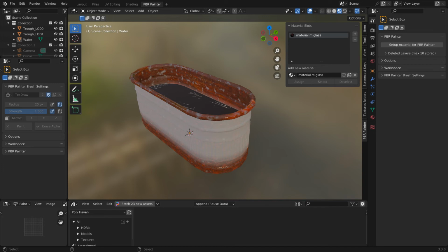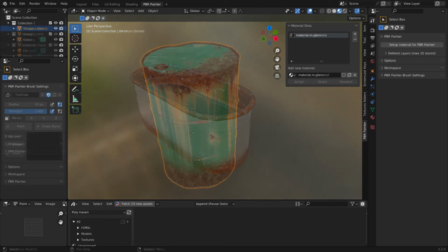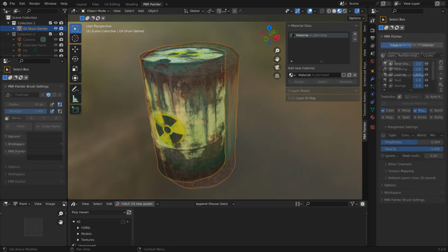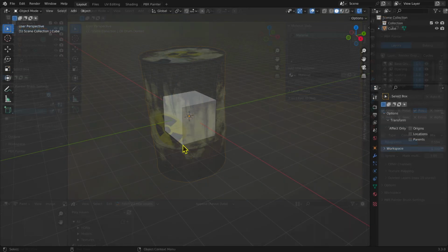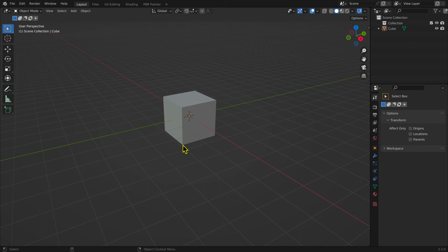Using masks, you can add effects such as dirt, grime, rust, edge wear, paint cracks, etc. Then you can bake out the diffuse, normal, and parameter files needed for import of a Blender asset into Trainz. As an add-on, integration into Blender and the ability to create the output files needed for Trainz makes PBR Painter ideal for texturing Trainz assets.